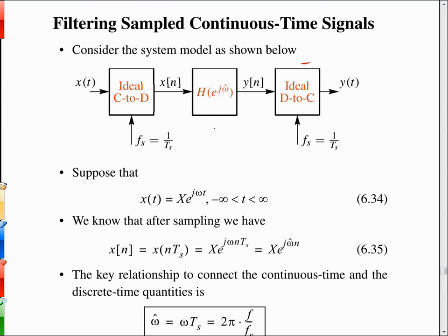It says if you can instantiate the hardware, namely the analog to digital and digital to analog, and then have the DSP microprocessor, FPGA, custom ASIC, whatever, sitting in the middle to allow you to flow samples in and out through some difference equation algorithm, then you can tell somebody, I can build almost any kind of filter that you could imagine, and I can make it flexible. It can be in software. I can reconfigure it on the fly. I can do all these great things with it. Just let me tell you about it, basically.